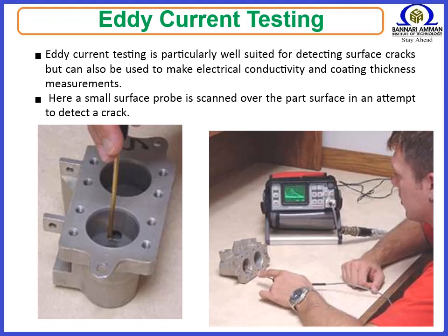Electromagnetic testing is a general test category that includes eddy current testing, alternating current field measurement (ACFM), and remote field testing. While magnetic particle testing is also an electromagnetic test, due to its widespread use it is considered a standalone test method rather than an electromagnetic testing technique. All of these techniques use the induction of an electric current or magnetic field into a conductive part, then the resulting effects are recorded and evaluated.